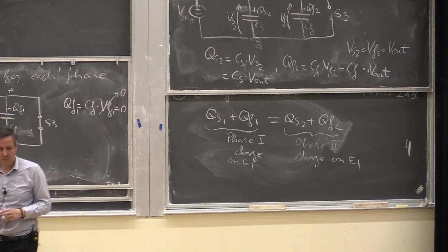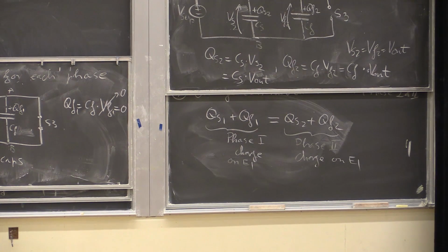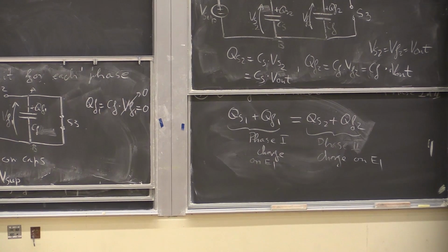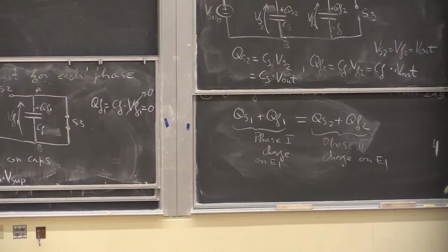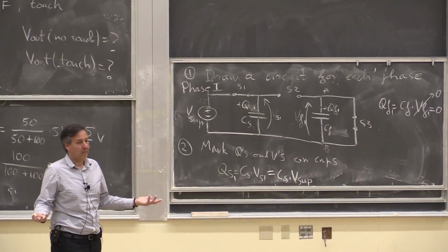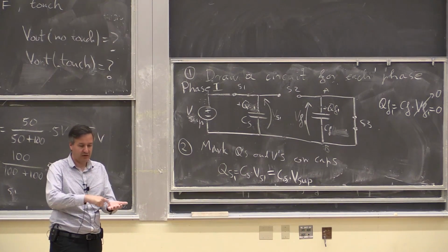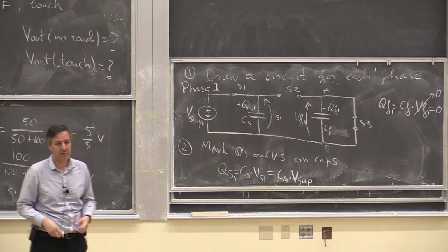Yes? What's doing the switching? What's happening during the switching, you mean? No, what is performing the switching? Oh, what is doing the switching? Some controller. In the lab, that's your Arduino little microcontroller. In the phone, it's also a processor. So some digital block does it. In fact, when we do the oscillators in a few weeks, this could actually be an oscillator on its own that periodically turns on one and then the other. So it's like a clock, and the refresh rate could be, let's say, a few tens of kilohertz. That's faster than your finger action, and that's enough.